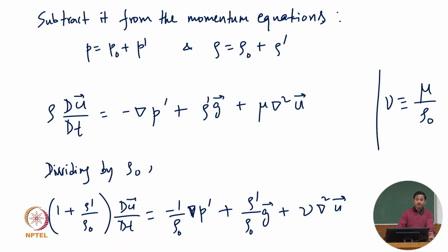If we had a Coriolis term, you can just divide the Coriolis term by the reference density rho naught. This will not change the use of this approximation here. We'll only keep the rho prime whenever it appears with gravity. As you can see, we have variations with multiple terms, primarily in this acceleration term, where we have this variation of density multiplied with du dt. This makes calculations and numerical simulations complicated.